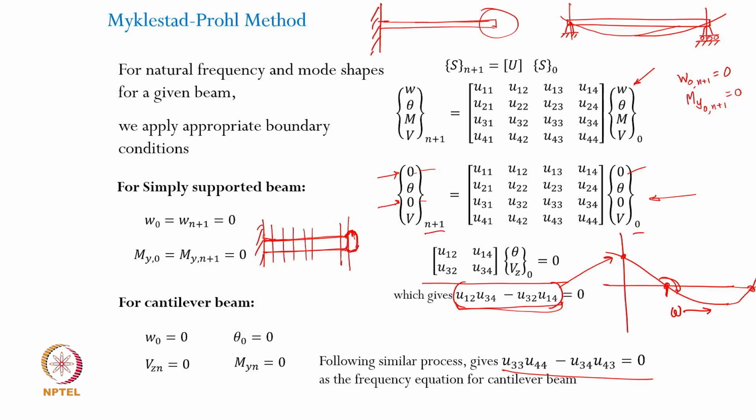So the transfer matrix corresponding to the end segment here will have, in your point mass, the mass which is located here, mi omega square. This mi will be not only the mass of this segment, but I can use this mass, the tip mass, to get added to it.